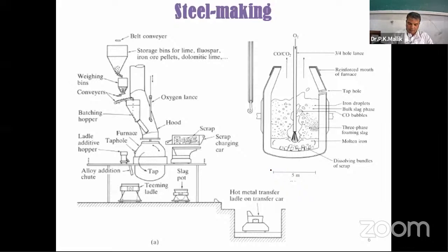This scrap coolant is required to avoid the temperature of the molten steel exceeding 1923 kelvin, which would also cause unnecessary refractory reactions. And this is not a single heat transfer process. Here three transport phenomena occur simultaneously: mass transfer, heat transfer, and fluid transfer mechanisms are all involved.